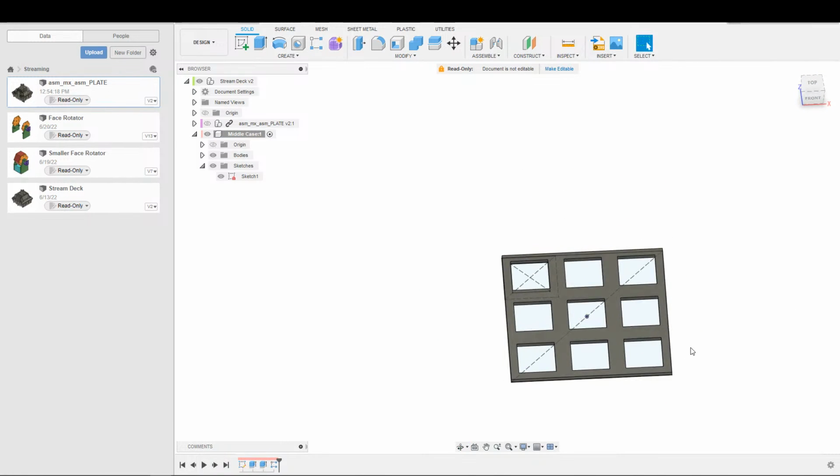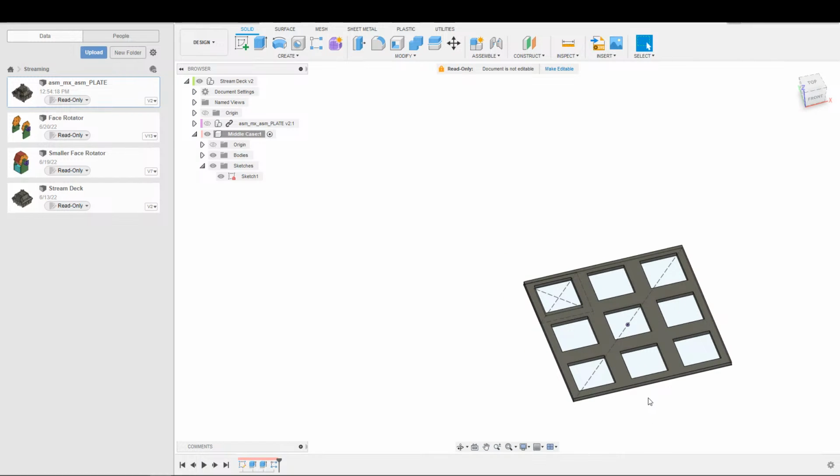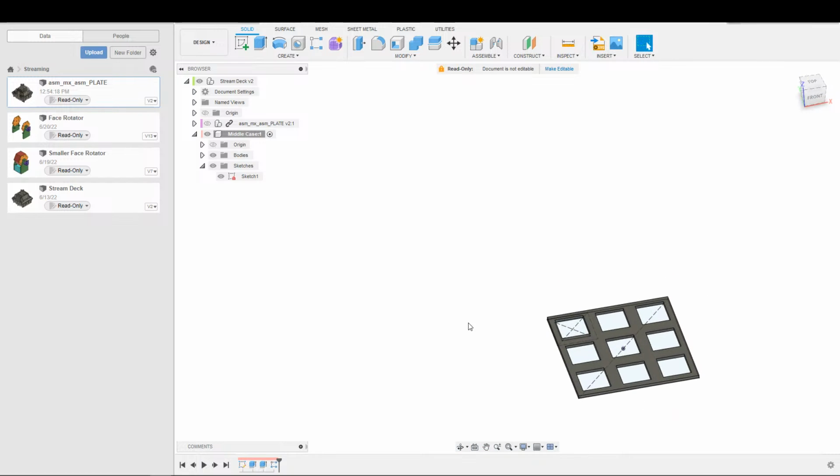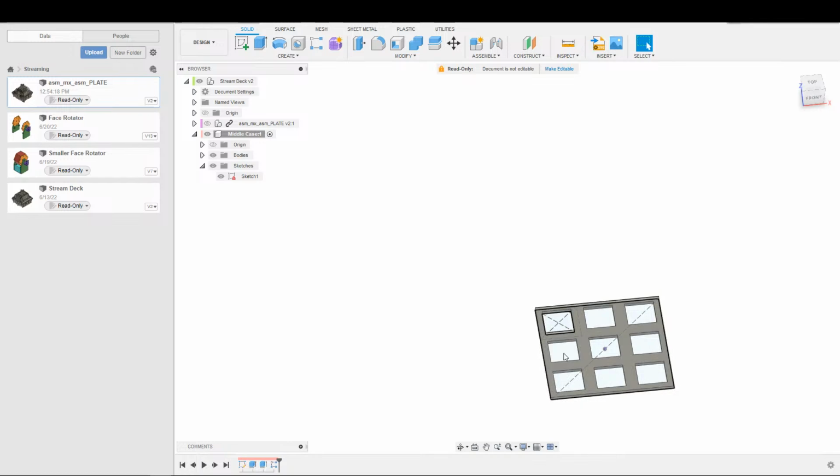That will hold the switches themselves, and then we'll put a box around this. Again, we only need just so much in each of these cases, because we'll do a base case that will hold the Arduino and anything else that we need. So, for example, it'll probably have JST, I'm thinking, just because I trust the JSTs to stay connected more than the DuPonts. So I'll probably use JSTs for this guy, and we'll have JST connectors in the back of it to connect more modules exterior. Otherwise, as I said, obviously we have the boundary, the meat around the edges here, and this 20 millimeters should be more than enough space on the inside here.